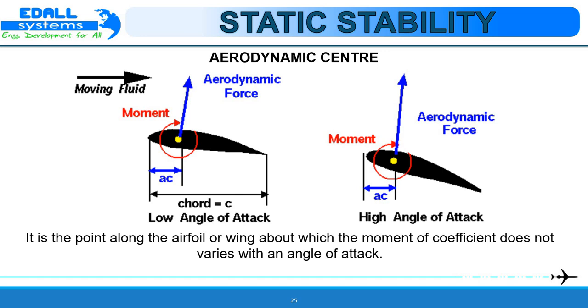is applied. It has been found both experimentally and theoretically that if the aerodynamic force is applied at the location of 1/4 chord back from the leading edge on most low-speed airfoils, the magnitude of the aerodynamic moment remains nearly constant with angle of attack. Using the aerodynamic center as the location where the aerodynamic force is applied eliminates the problem of the movement of the center of pressure with angle of attack in aerodynamic analysis. For supersonic airfoils, the aerodynamic center is nearer the half-chord location.